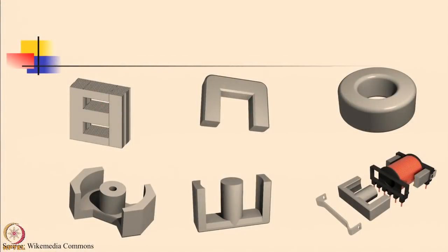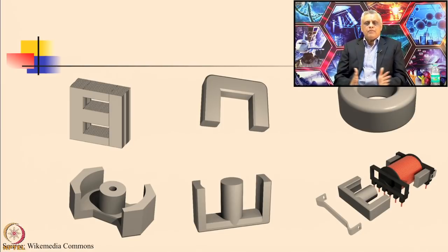You can put that on, and then you can insert the magnetic core. For example, it is shown that an E core is being inserted. One has been inserted already from the far right side, and another can be inserted from the left side, as you can see. These are symmetrically inserted, and due to the dimensions they exactly match each other and touch each other inside the bobbin, and a closed path is formed for the flux created by the coil wound on this bobbin. On the leftmost side there is a metallic clamp which is used to hold the two E's of the core together so that they do not move. So that is how you realize it.